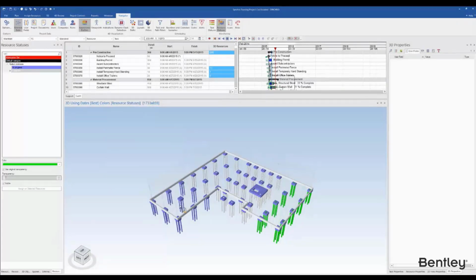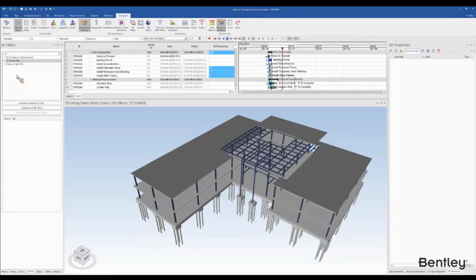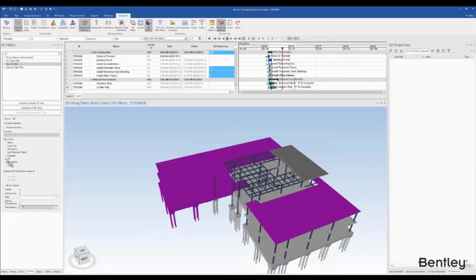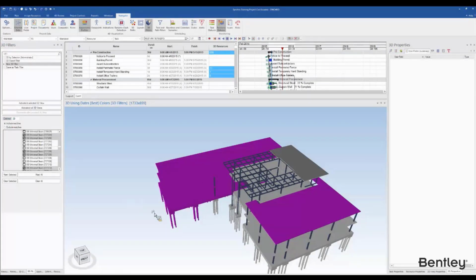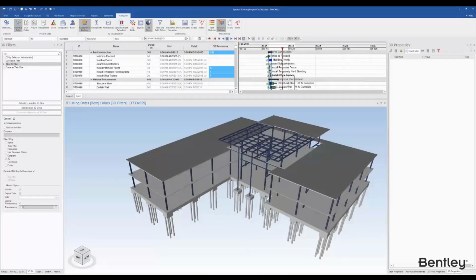We've got a 3D filter color mode. Let's see what that does. That would be based on, as the name suggests, 3D filters. So let's say I have a new 3D filter here. I'm creating a filter based on my selection mode. So let's say all these elements are in my 3D filter. Then I can say, okay, make the elements which are filtered using that filter a color.